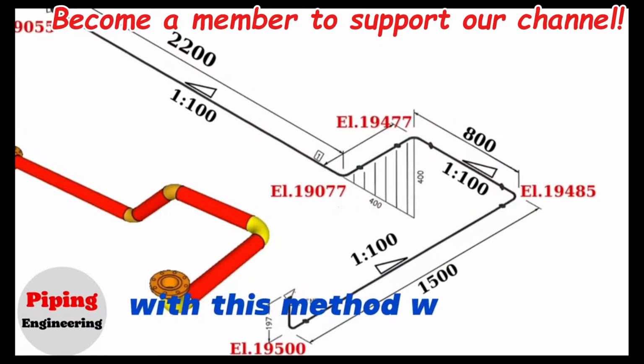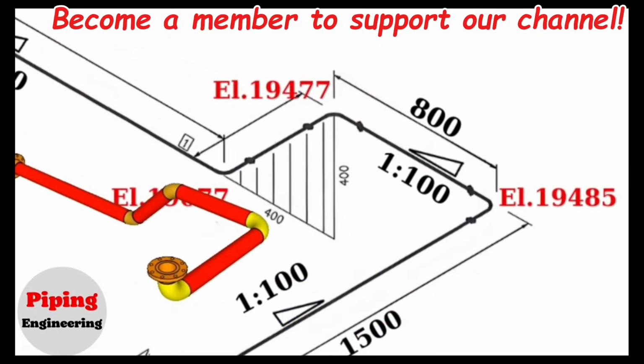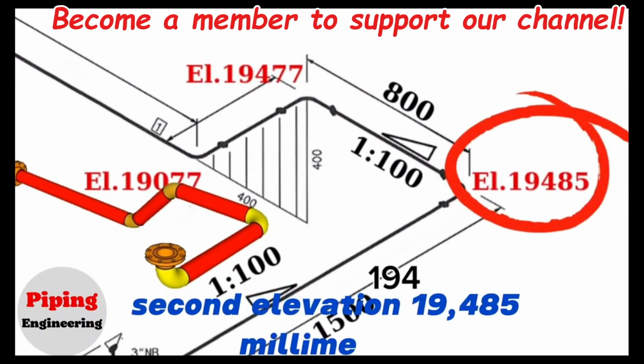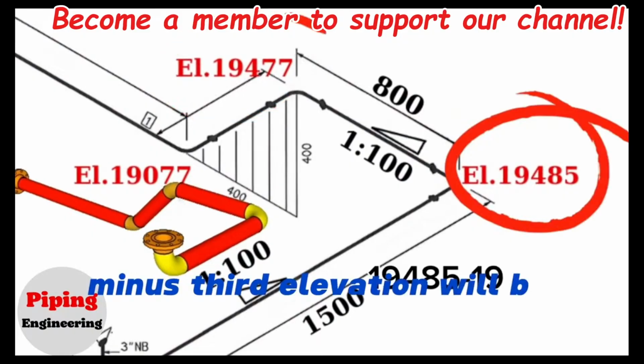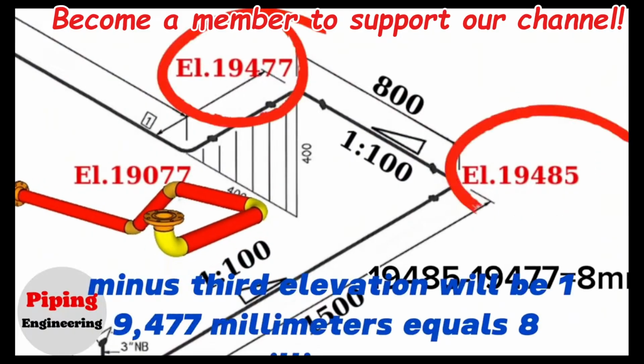With this method we can calculate the difference of the levels in the second and third rotations. Second elevation 19,485 millimeters minus third elevation 19,477 millimeters equals 8 millimeters.